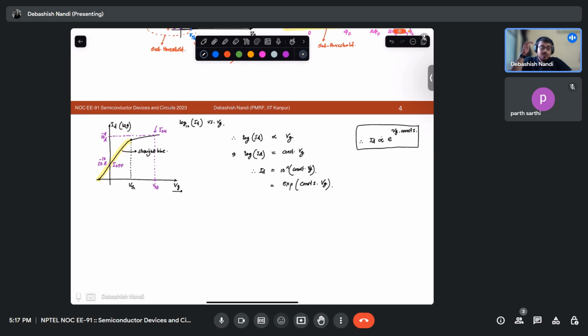So what kind of current is this? In MOSFET, in the convention we have seen so far, the current is, let's say, half mu n Cox W over L times VGS minus VTH whole square. This kind of current, how did you find it? Do you remember the process? Which kind of transport did you use? You used your drift mechanism, right?